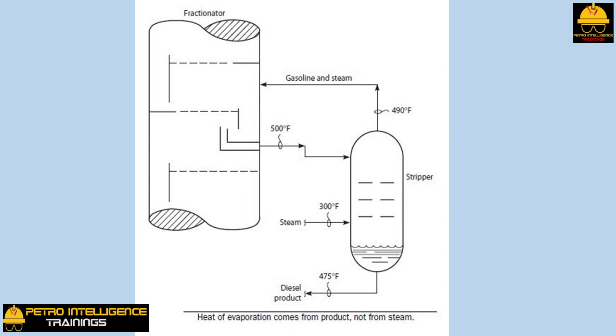The stripper bottom's temperature increased by 35 degrees Fahrenheit, and the flash temperature of the diesel product increased from 120 to 175 degrees Fahrenheit. High liquid levels in the bottom of the stripper will also reduce stripping efficiency. A liquid level above the steam inlet will cause the stripping trays to flood. Flooding vastly decreases tray efficiency and hence stripping efficiency. Tray deck dumping also greatly reduces tray efficiency. Unfortunately, steam strippers can have widely varying vapor rates between the top and bottom trays of a column.